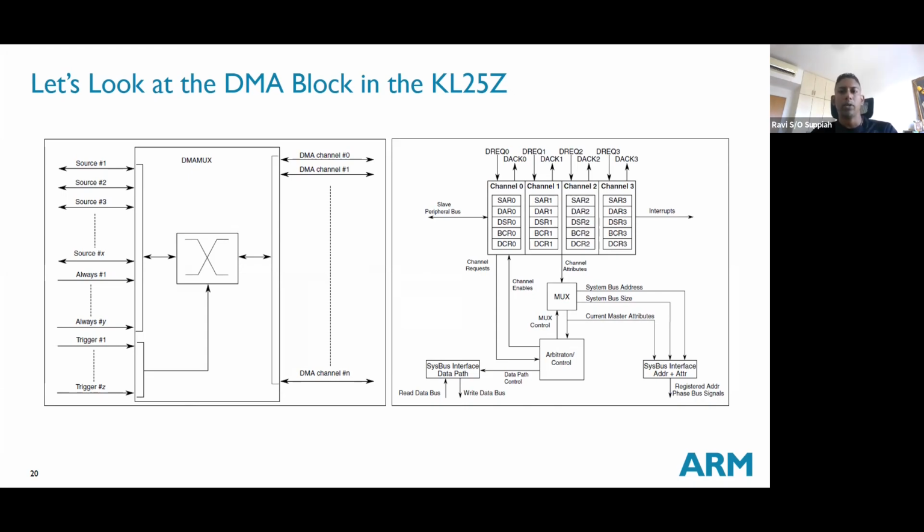So if you think your system would benefit from this kind of fast data transfer, then you probably want to look for a controller that has a DMA block already built in, and that can help you. It's always important to have a good overview of the hardware you are dealing with, and to see whether it is suitable for whatever project you're working on.